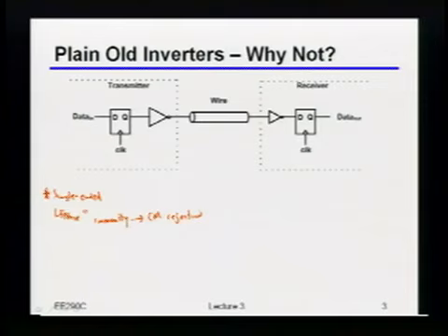I mean, in general, you need to have a good noise margin for the inverter at the receiver. Okay, when you say noise margin, what exactly do you mean? I mean, if there's any coupling, it may give you a wrong logic level. Okay, coupling from where to where, for example? Any other digital circuitry nearby, like ground switching, supply switching, something. Okay, so you're sort of saying something about supply switching or ground switching. So actually, that's a very good subject here.